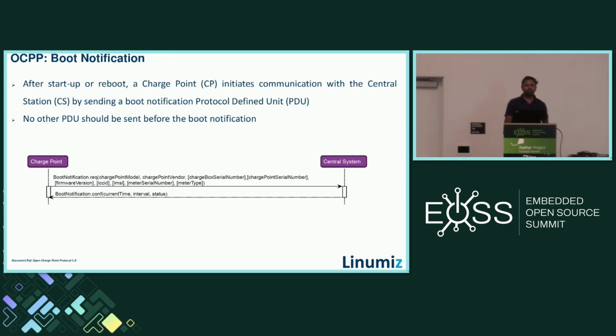Okay, so boot notification is the PDU message which is the first message the charge point sends to the central system. The central system discovers that there is a charge point available in the network using the boot notification message, after a startup or a reboot, when the charge point initiates communication with the central system.